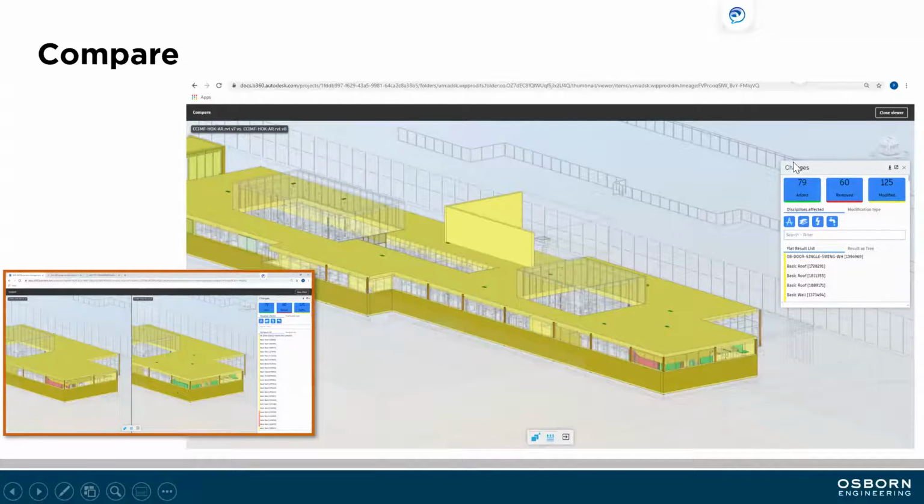If any of you are familiar with Navisworks, this is a similar idea, where you have a file tree over here of all your different systems, and you can isolate them that way. It's just a really good way to comb through models to see where the major changes are that might not be as evident just looking at a 2D drawing.